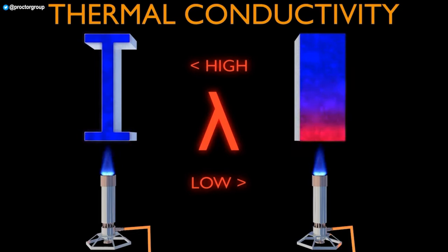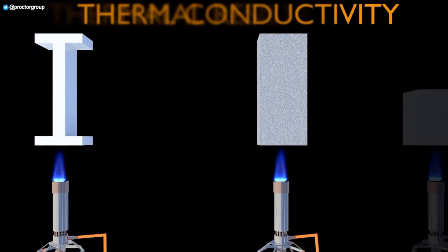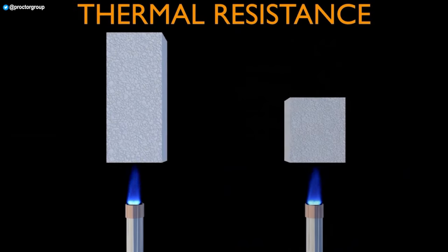Thermal conductivity is useful for comparing materials as it does not account for thickness, making a straight comparison of how good is the insulation easier. It's less useful, however, when we need to consider a specific application, such as roof or wall, as it doesn't account for how much material we're using.